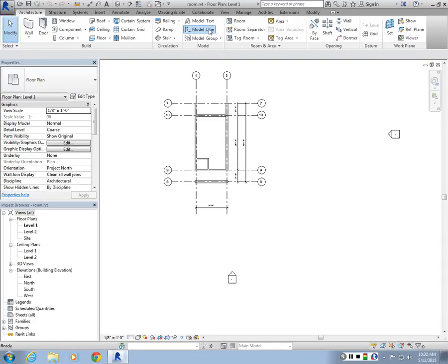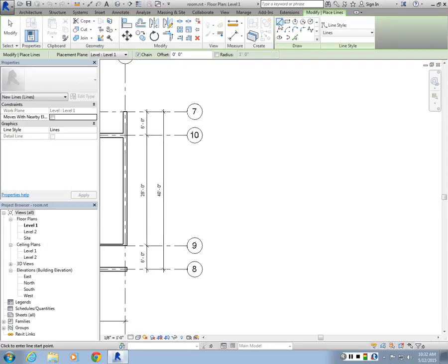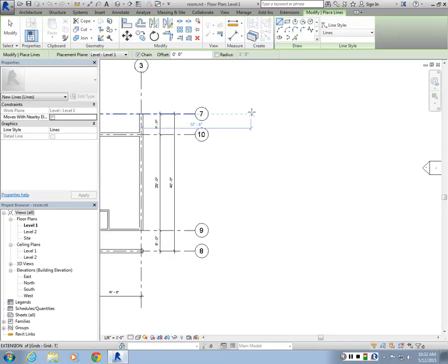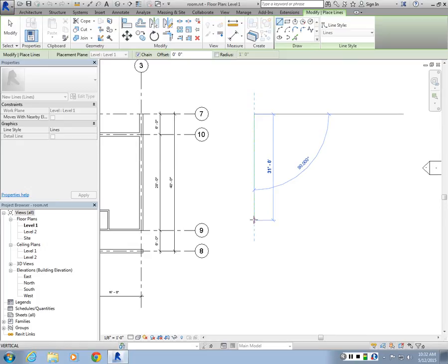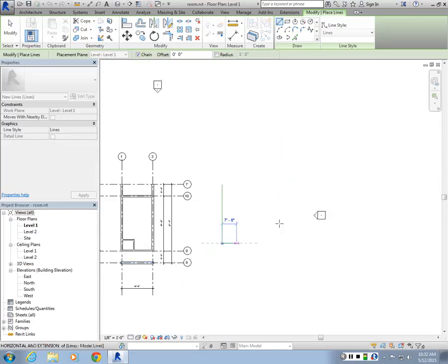This is basically a two-dimensional drafting tool. So you can technically create rectangles, any type of lines, or any other geometric figures as well, like circles, polylines. What you would do is enter the basic dimensions, so you can start drafting the overall outline for the unit. So let's say for the hotel room, I want the whole thing to be, let's go for like 30 feet. If it's too large, we can scale it down.